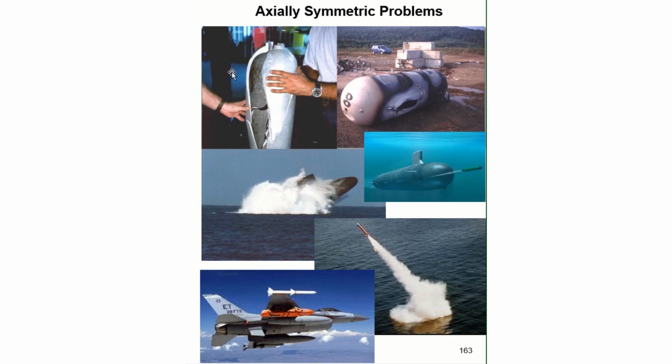This is a scuba tank that has failed, and this is a large water tank that failed. And you can see here that in this failure, the crack is longitudinal, and we have the same crack in this pressure vessel over here. You should remember and understand that this is not by chance.